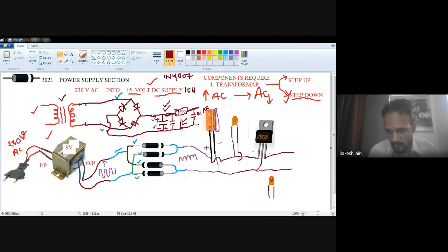I use a jumper wire to connect with the minus terminal, the middle terminal of the voltage regulator IC. For one more capacitor, I move it at the upper side so you will not be confused. The first pin is connected with the third pin of the voltage regulator IC, and the second pin of this capacitor is connected with the same ground.